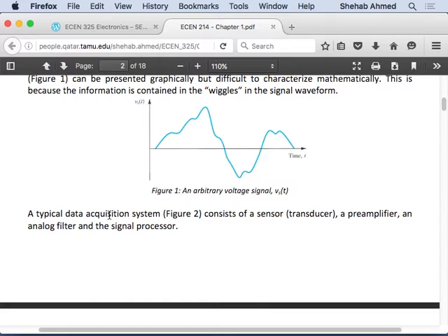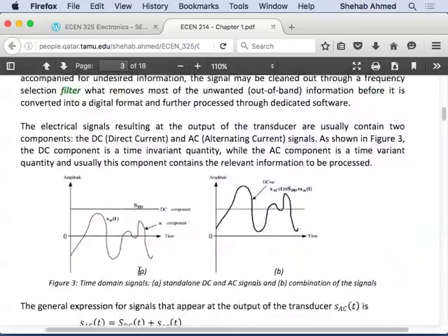I have to measure it, and then sometimes I have to amplify it, because my computer accepts analog signals between 0 and 3 volts, for example. And the sensor is giving me 0 to 10 microvolts. I need to take that 0 to 10 microvolts and amplify it using my amplifier. So the amplifier will have to process the non-sinusoidal signal in this case. So you have to characterize the amplifier to make sure you understand how it's going to operate for a non-sinusoidal signal, right? That's the objective of what we want to do.